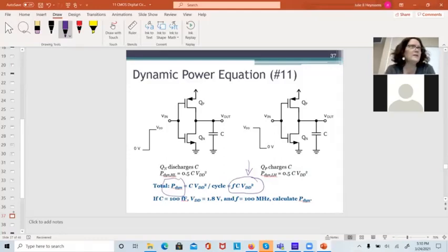But the biggest thing, and this has been going on in my lifetime, is VDD squared. Power goes down as VDD squared. So the old TTL parts that you used in the 110 lab, 5-volt logic, that was standard until the late 80s. And then they went to CMOS and down to 3.3 logic. The power went down by a factor of 3.3 squared over 5 squared.